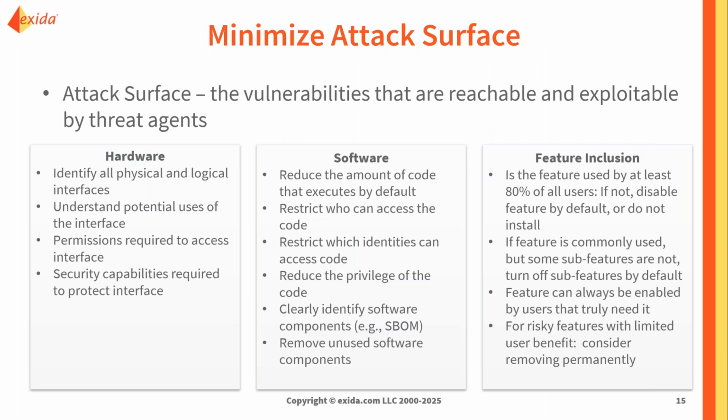In addition to including security as part of the development lifecycle, there are also important steps that need to be taken to minimize the attack surface. And we can think about this from a hardware standpoint. So looking at a controller as an example of an embedded device or a component, thinking about, well, what interfaces are available that someone could use to connect to that device. And so for each of those interfaces, what is its intended function?